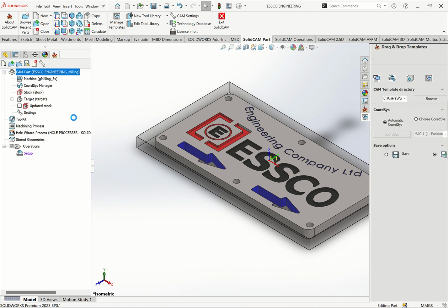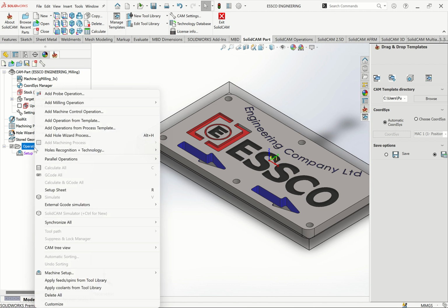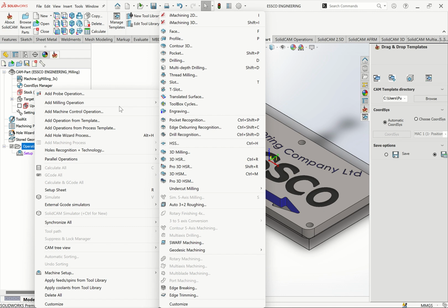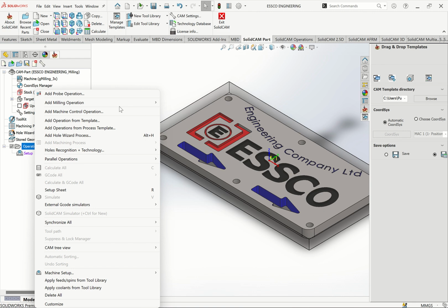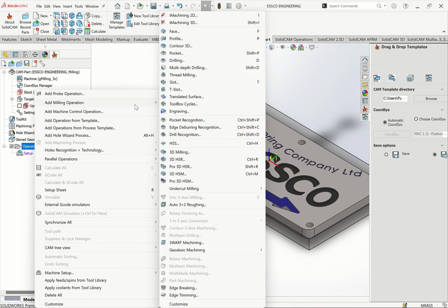First thing is, normally you can do either drilling or facing. But if your first surface is not good, basically you have to start with facing. So I'm assuming that the stock is not well prepared, so start with facing, or you do surface grinding before you bring it to a milling machine. But if you don't have a surface grinding machine, you can do facing.